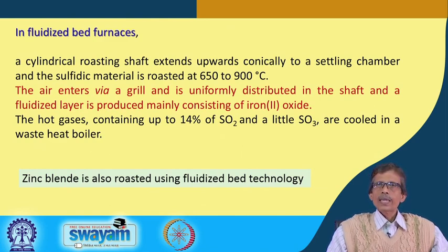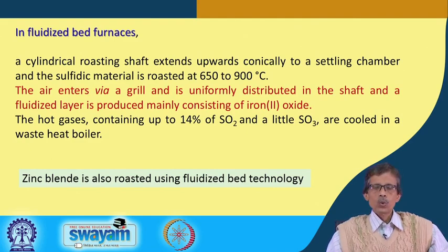the process. So, like FeS2, we can have some other sulfidic ore, which is zinc sulfide, ZnS, known as zinc blende, which can also be utilized for this purpose using the fluidized bed technology. Depending upon the availability of the ore, whether we get FeS2 as a good or regular supply in the near vicinity of that industry, we can go for FeS2; otherwise we can go for zinc sulfide for its production of SO2.